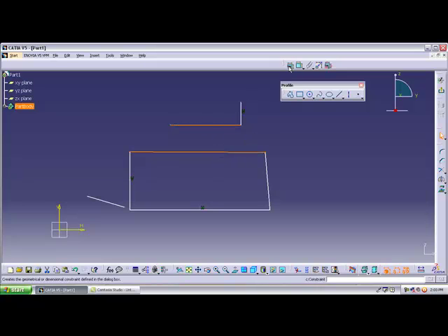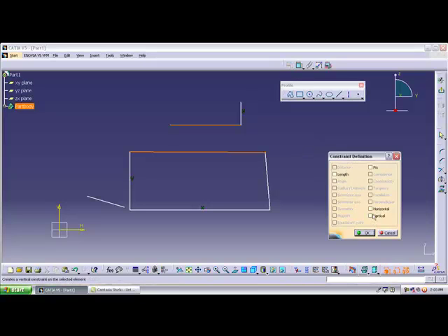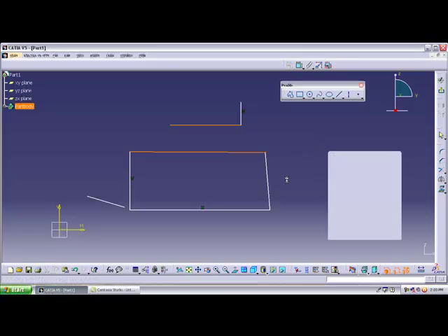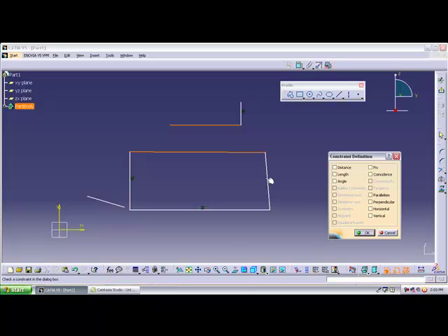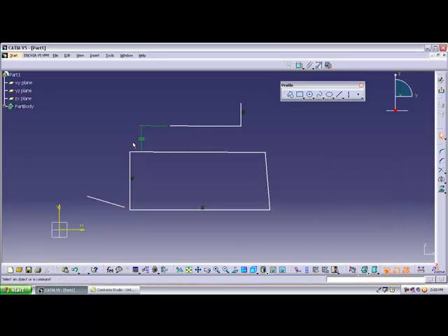After that, select the geometrical relation. I want to add the relation as parallel. Sorry, it's not getting. One more time. Select the two lines by holding the control button. After that, select the constraint. Then you will get the possibilities which can be applied with two lines, that is parallelism. Okay, so it means that these two lines are parallel.